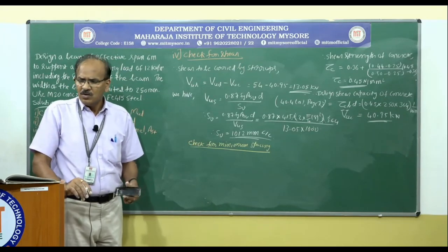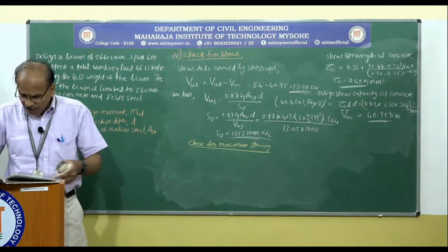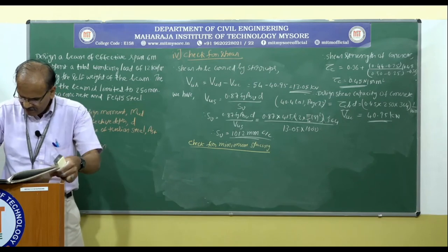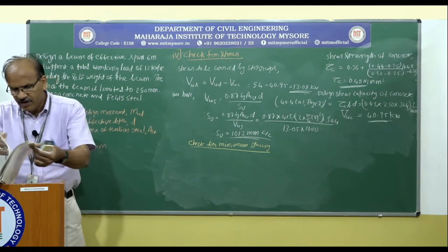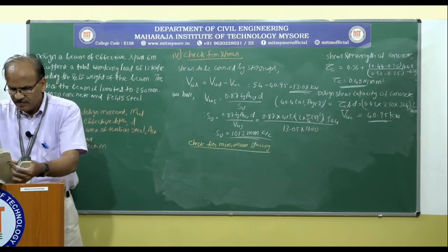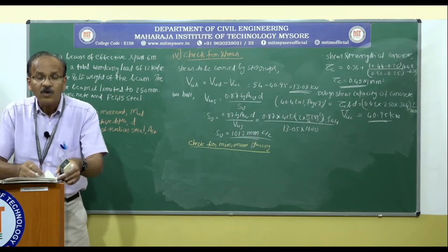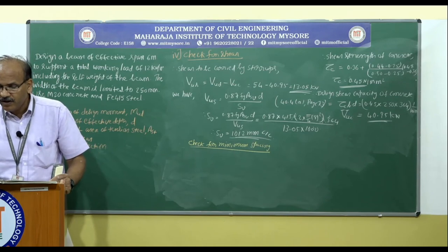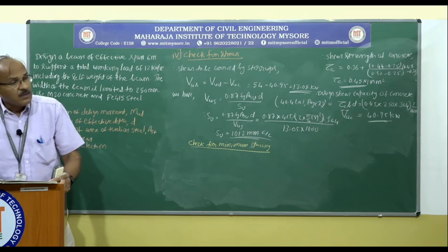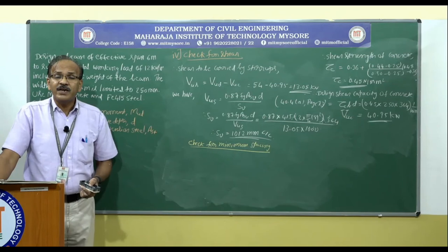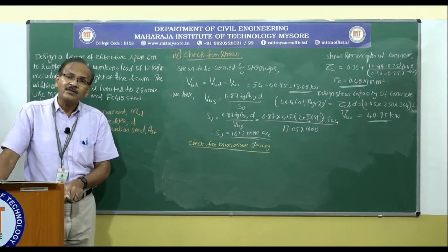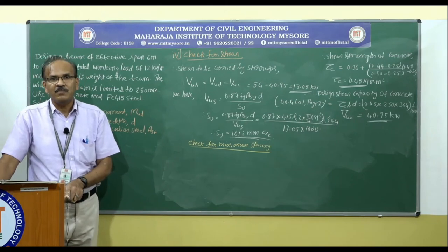No. So again, if you open page number 47 of the code book, 47 and 48, please open it. Under 26.5.1.5, it says the spacing should not exceed 0.75D and 300 millimeter.